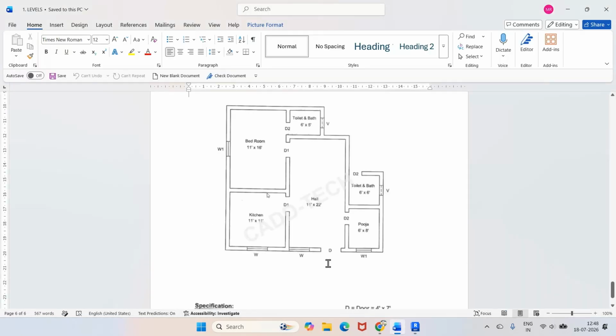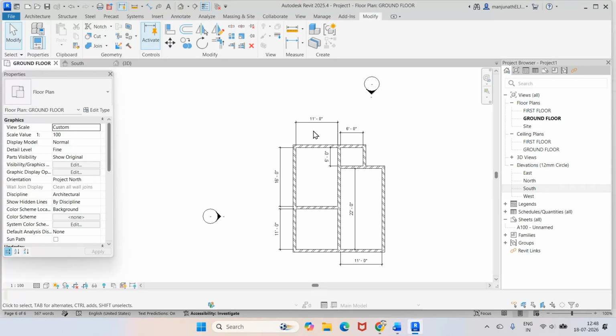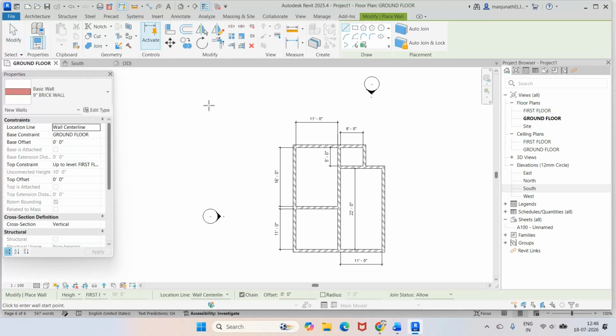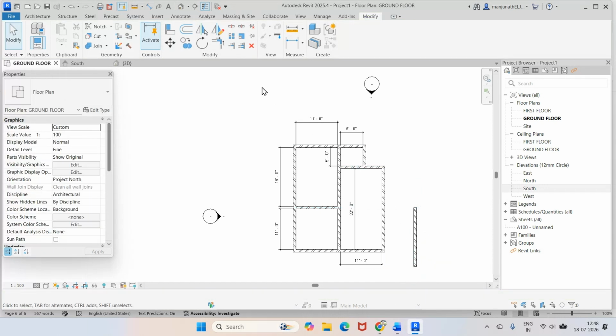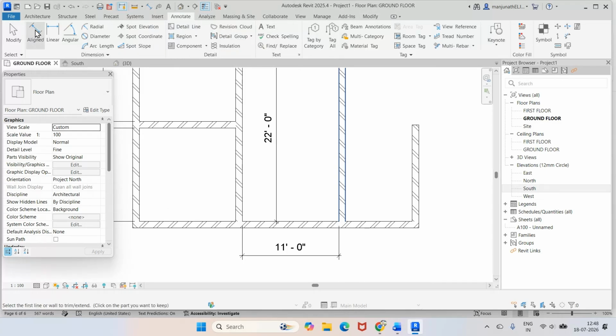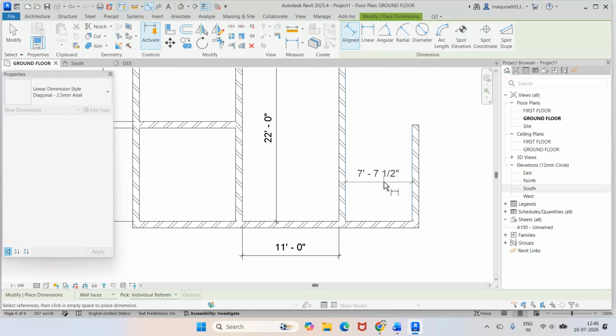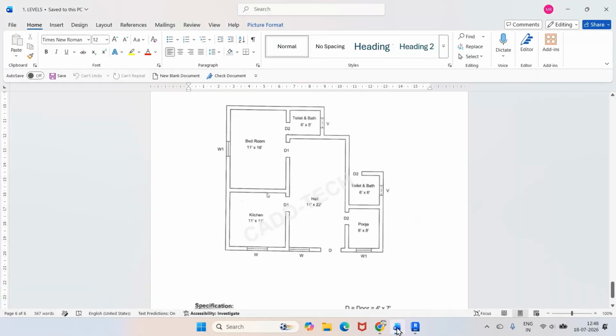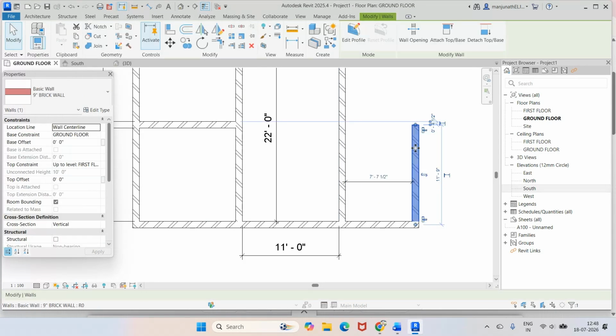Similarly, what I want is I want to draw a wall here from this 6 feet. So to do that, I will just go for wall, WA. Okay. Select on this side and you will try to draw this line. Now you go for trim corner between these two. Then I want to go to modify, go to annotate, go to dimension, that is the align dimension between these two. So here, this dimension to be 6. So you just click on modify, take the dimension as 6 feet.